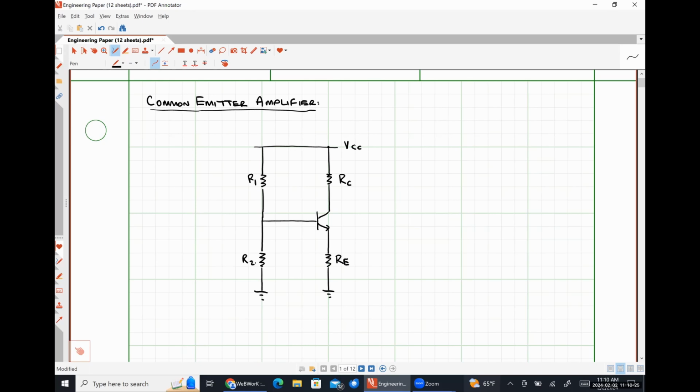we are going to see some capacitor that I'm going to call CN. And this capacitor is typically very large. And by very large, I mean millifarad to microfarad range, okay? The reason why we put a large capacitor here is because we want this capacitor to look like an open circuit to DC signals and a short circuit to AC signals.